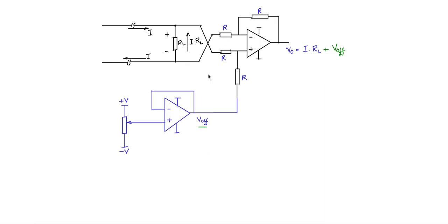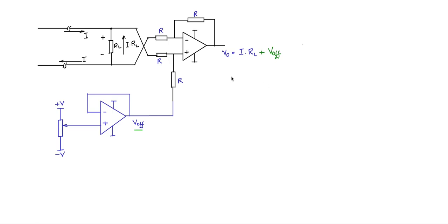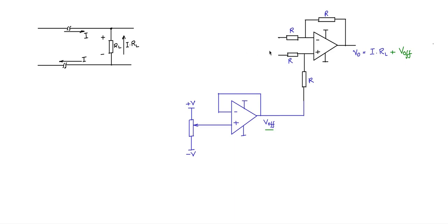So let me copy this here and make some space, and I will make a cut here, okay, and I will push this, make some space there. So here I will include the instrumentation amplifier topology so that these 2 points can be buffered so that they don't get loaded, and you will get precise and accurate results. So I will have 2 op amps in this fashion, VCC and VEE, VCC and VEE.